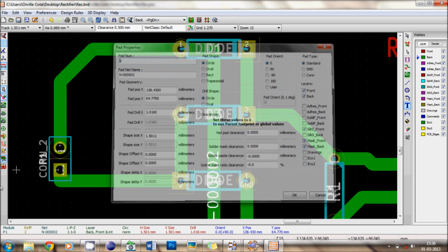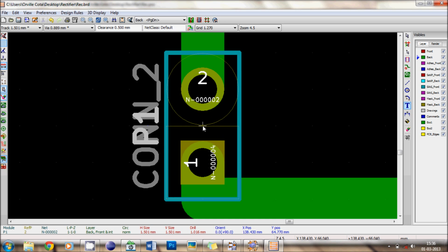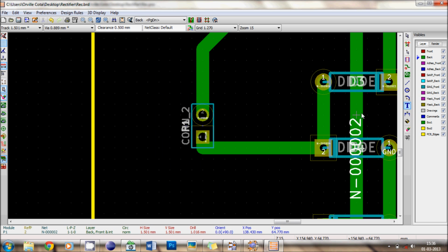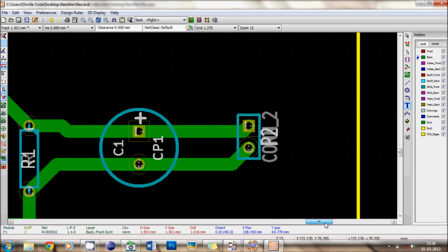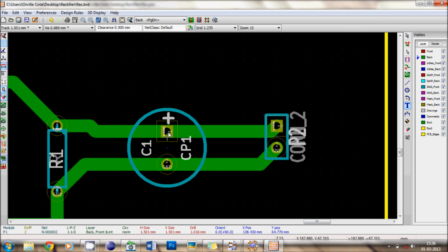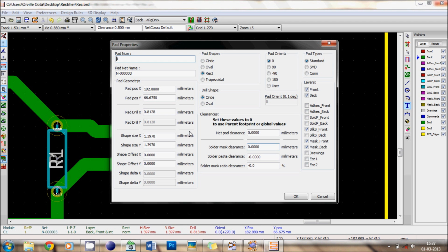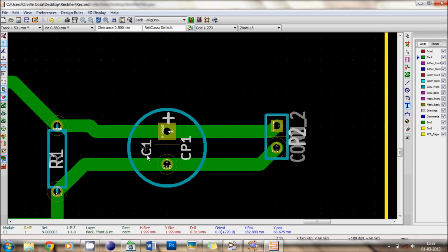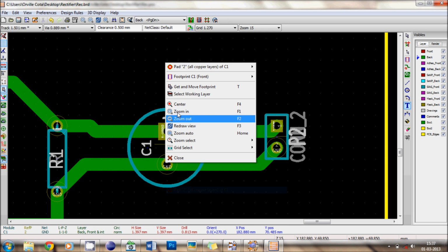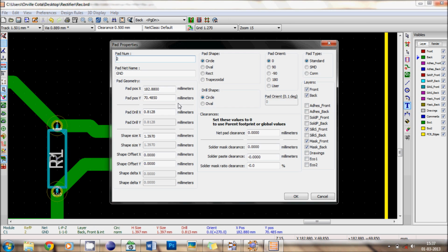It's actually not possible to make it a bit bigger because you can see the clearance that is there, the 0.5 clearance that we gave. If I make it bigger, it's going to clash, so I won't be able to give this. So in the others, we will give the editing. Edit. Press 2, enter, 2, enter. Okay. Edit.